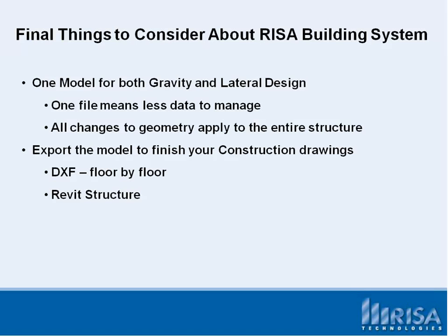I can send it out to a straight DXF file format. And just like we saw when we saw floor by floor with the import, it's similar to that where I can export it. And then also I can export it to Revit Structure. That same exact Revit Structure model that we just saw, we can update it with all the correct sizes that we had from before. So it's one round trip when you use a Revit Structure model. A DXF file format is not going to be a round trip, but Revit Structure is a round trip. So any changes that happen on either end, we can send it back and forth.